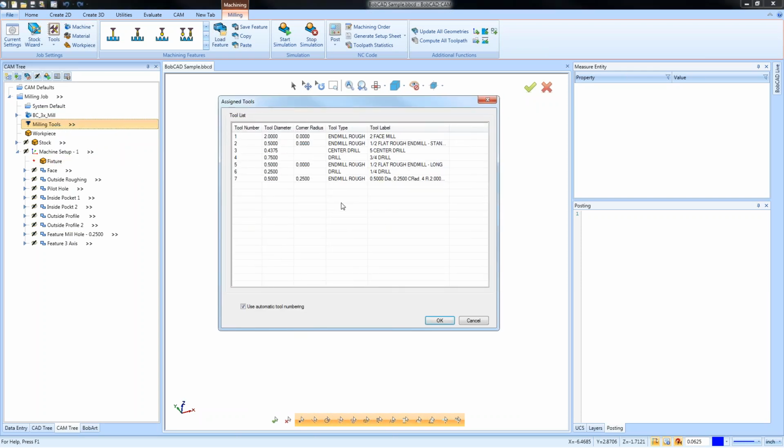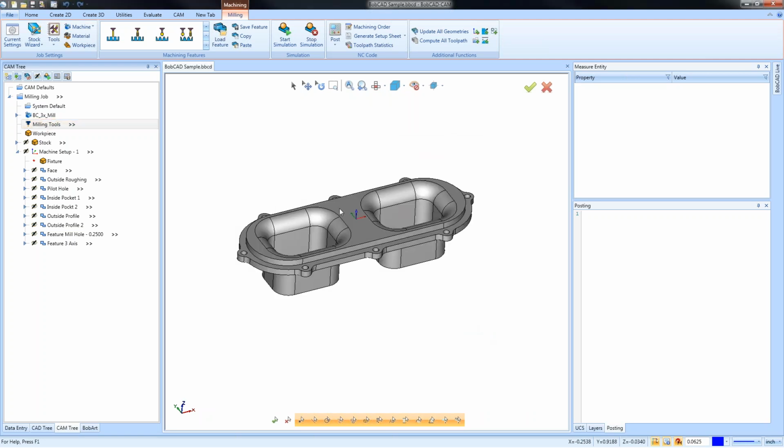I recommend, whether you're a new user or whether David, NextWave, I think, uses WinCNC. We definitely have a WinCNC post processor. So you have a job set up, you programmed it with all the different tools that you're using. Now you want to verify what tools you've used and what tool numbers are being used. This is a step I recommend for new users prior to posting, right?